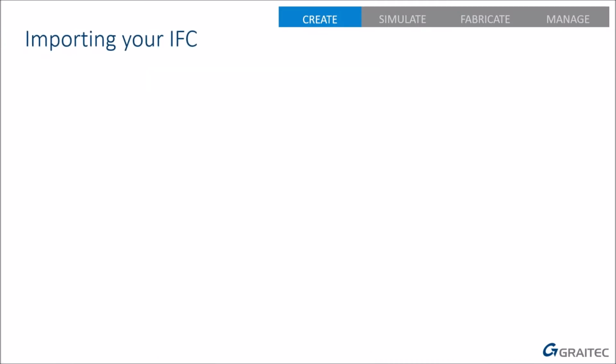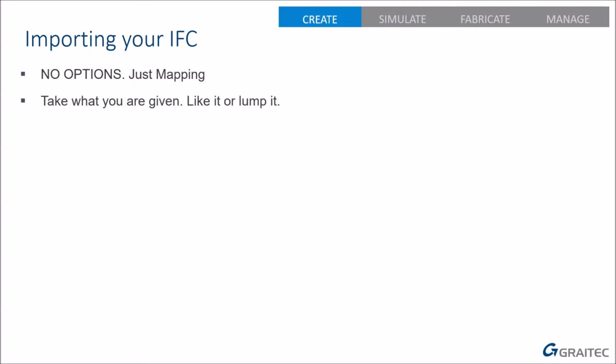Okay, but we want to actually import the IFC as intelligent data. So let's assume you have got an IFC file that's got some intelligent data in it. Well, there's very few options, or basically there's no real options about how to import, but you will be asked about mapping when you import. When you do that, you've asked all the questions for mapping. Basically, you just have to take what you get. There's nothing we can do. Again, there's no options. So I can't try again and do a different option to get a different result. I'm just going to get what I get, take it or leave it, like it or lump it.